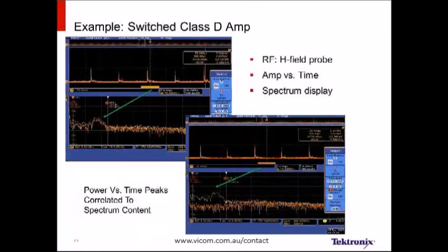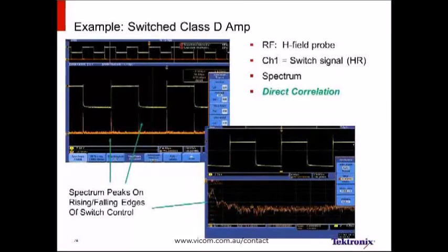From an EMI perspective, this is not good because that's directly correlating now with the AM or the FM broadcast band. I should point out, though, in this particular experiment, I was using an H-field probe directly over top of the actual switching IC itself. I haven't yet probed it, but in this next slide, I start probing the switch or the control frequency on